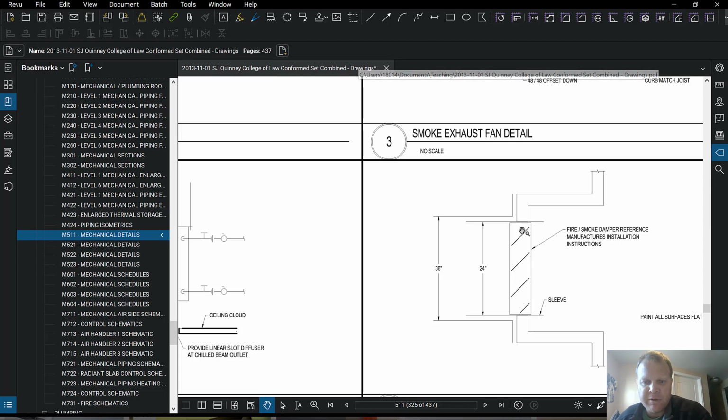It's just a damper, just like any kind of damper. They use dampers to adjust how much air is going through a room. Like remember if we were doing that VAV box. The VAV is variable volume, and inside that box there's a little circular damper that was motorized to control how much air is going into the duct. Same kind of thing. This is just going to either be open or closed. That's all this damper is going to do.